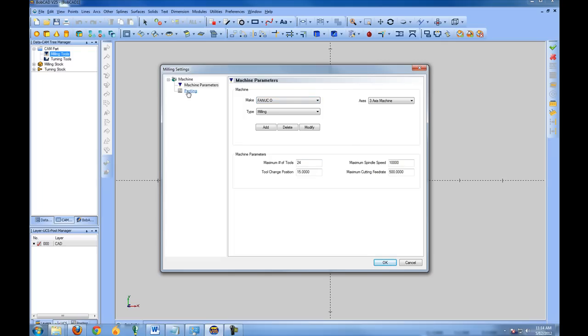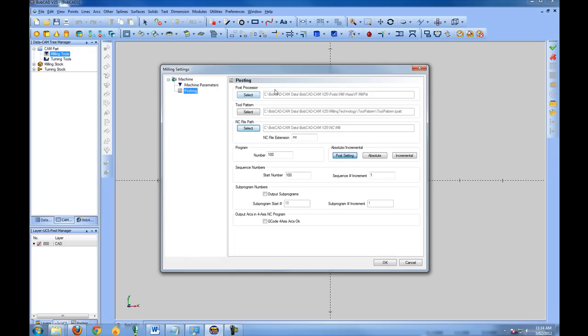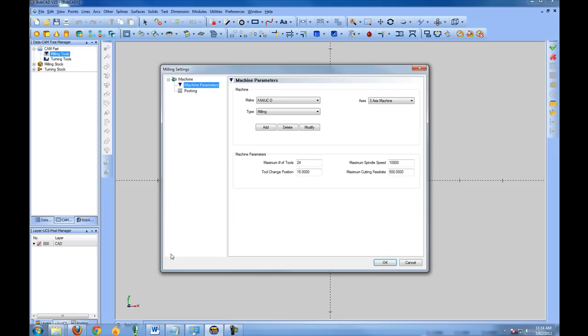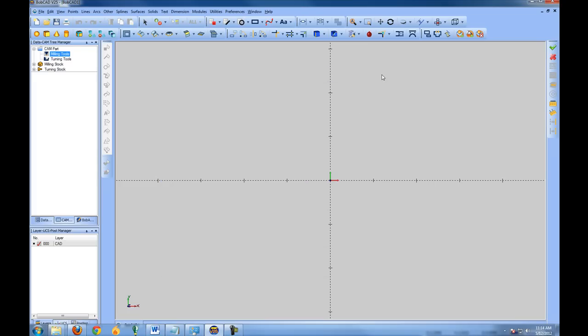When you change the machine make, it will change the post processor being used and several other settings within the software. So it's very important. One of the first things that you should do is come in, create your machine make, choose or install, and then choose a post processor to drive the machine. And then you'll be almost ready to get started programming with Bobcat.